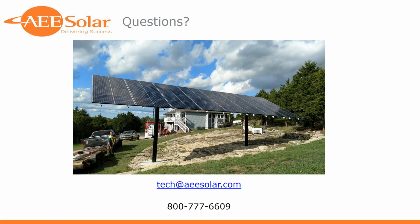They're not going to want that inverter to shut off completely, because as we get more and more PV on the grid, think about an event where the frequency rises to 62, and then in an afternoon, 5 to 10 to 20% of that generation drops offline. That's a really bad event. That's really taxing on the grid. So the reason a lot of these standards came to light was areas like San Diego and Hawaii, where grid operators knew they would have to have a way to keep most of that PV generation online, but maybe throttle back.